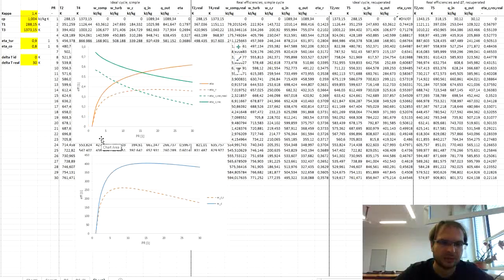And the pressure drops would actually show us that the maximum of the recuperated cycle can be somewhere around, let's say, 30-35% with the efficiency. So because of the actual limitations in the efficiencies also for the real cycle, if we take into account more of the effects and impacts, the recuperation is not actually considered option for the big gas turbine systems.